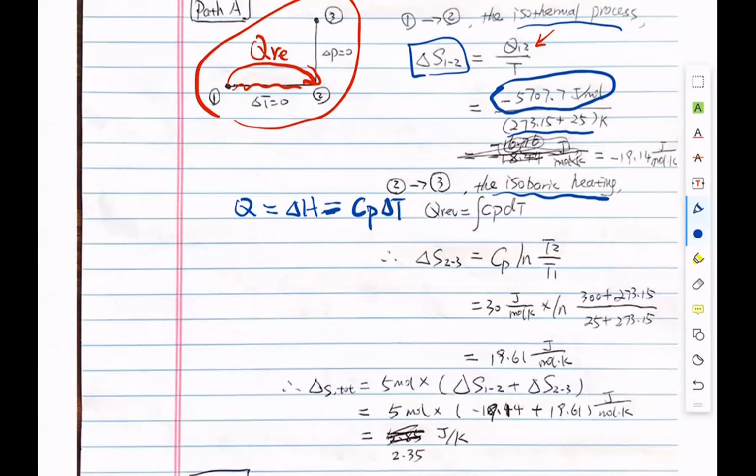So this is indeed the equation we are using. The heat is calculated through the Cp value, Cp dT, through the dH. So the small amount of reversible heat would be a small amount of the enthalpy change, Cp dT, and we just run the integration from 25 degrees C to 300 degrees C.